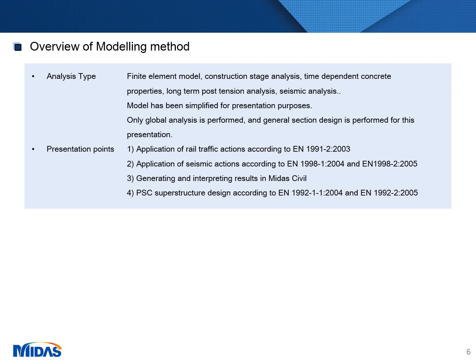Finite element model of the bridge is made in Midas Civil. The software supports construction stage analysis, time-dependent concrete properties, long-term post-tension analysis, seismic analysis. Model has been simplified for presentation purposes. Only global analysis is performed and general section design is performed for this presentation.